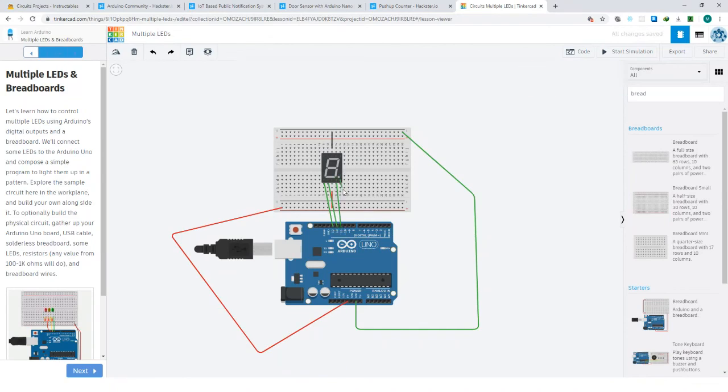Then the decimal point, let us put it on pin 10. We may need the decimal point if we need to connect it. And this wire should look black, so that when we're using the green, we are aware of what we're doing. So that is how it should be. Then, of course, we have pin 9, pin B, A. So where is B? Remember, this is B. Okay, so we take pin B and we can connect pin B to 9 here. Okay, and then so that it doesn't look so bad, let me just put some corner here.